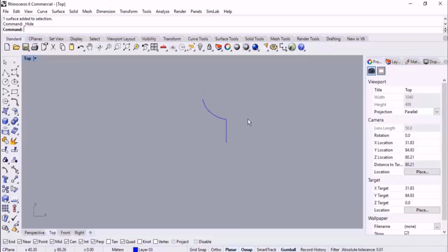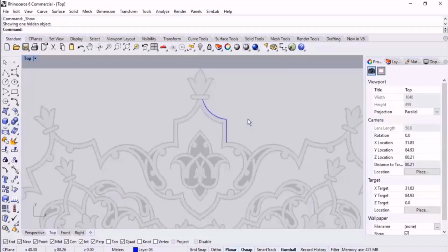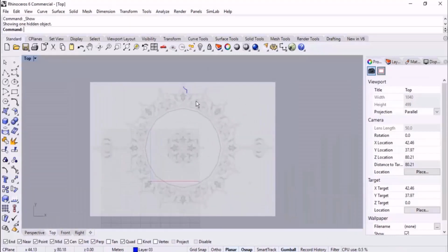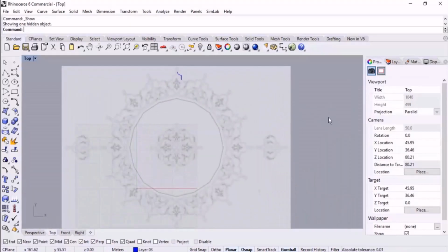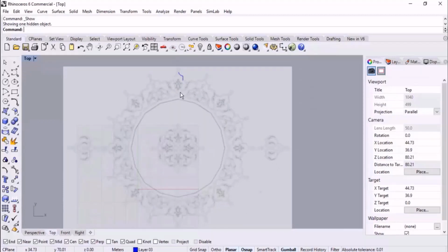If there are any problems or mistakes, you can fix them, or after the revision process, you can unhide it, which is Alt Control H. We use Control plus H for hiding the image, and then Alt plus Control plus H for unhiding it. So this was one of your homeworks that you should do,